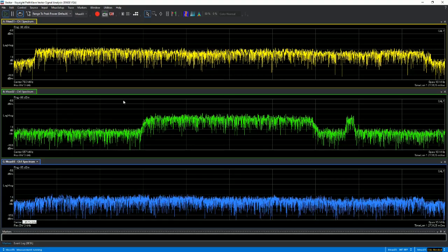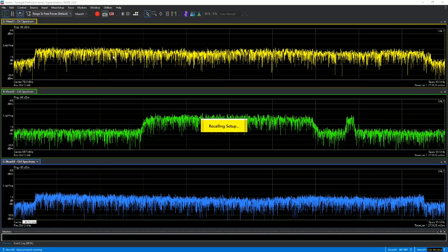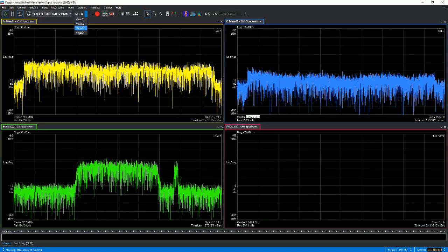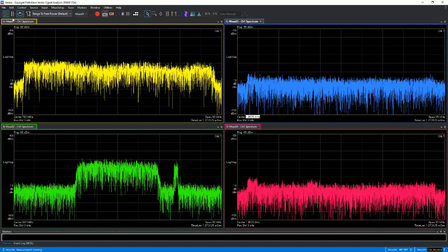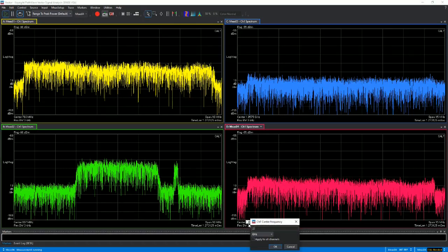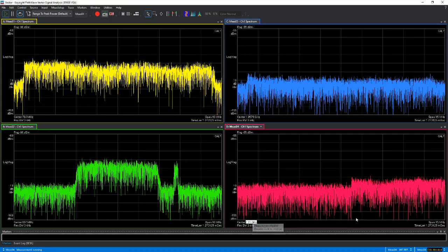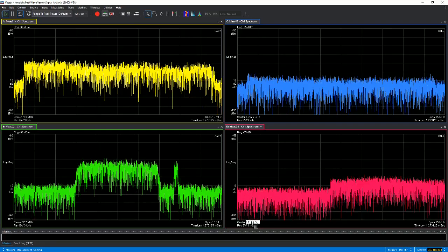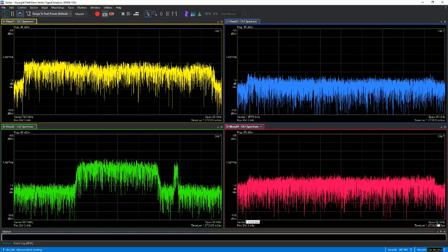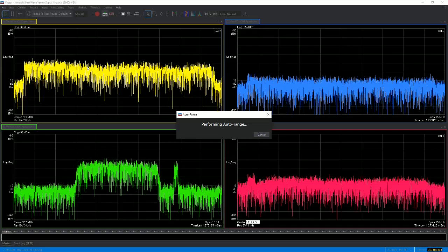Okay, about there. Let's add on another one. Let's go to duplicate measurement 3. So we have measurement 4 right now. Let's select measurement 4 and make it active. Let's set it to 2.11 gigahertz. And let's move it to the center frequency somewhere there. Then we can redo the adjustment.